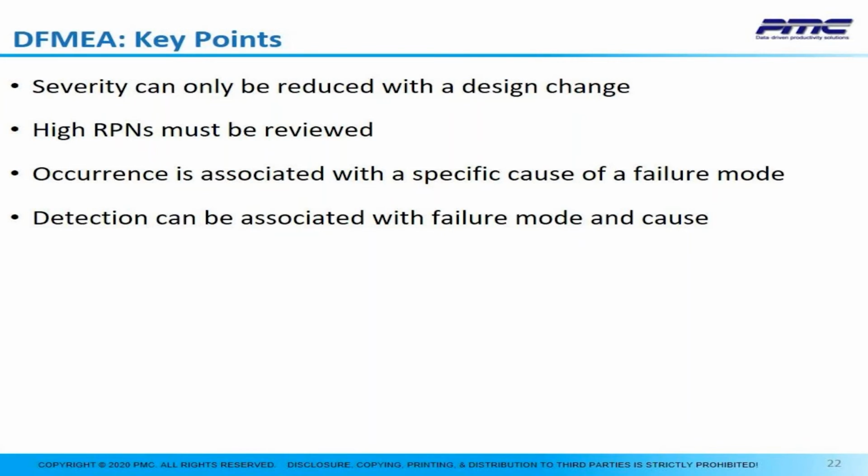The criticality number, the severity times the occurrence, highlights risk requiring preventive action. Use wording in descriptions to make cause effect logic apparent. Assume the design will be manufactured and assembled to the design intent. Design for manufacturability and assembly concerns may be included in the DFMEA if they have contributed to or been responsible for past failures.